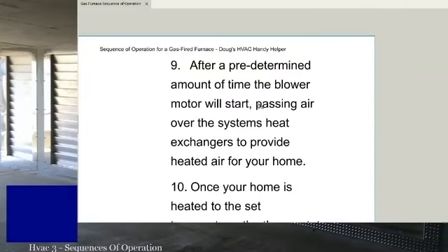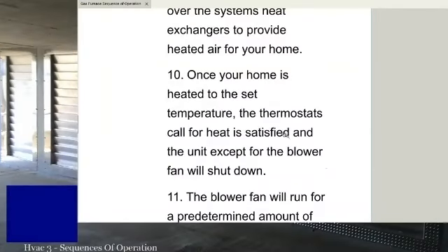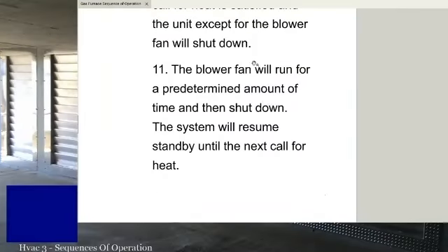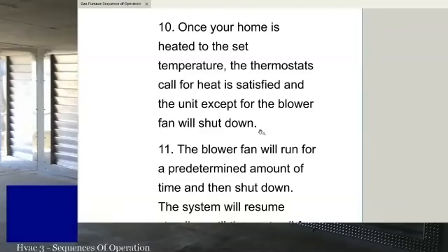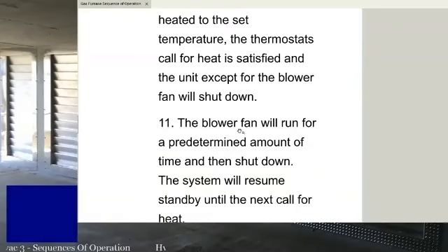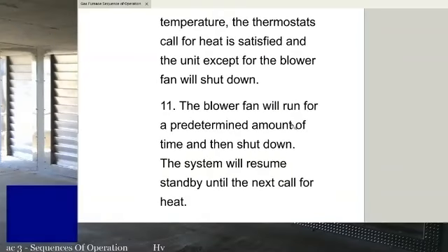All right. After a predetermined amount of time, the blower motor will start, passing air over the heat exchanger to provide heated air. Once the thermostat is satisfied, everything shuts down except for the blower. Sometimes the induced draft motor will run for a short period of time afterward to make sure all the gas is out of the combustion chamber. So that's a post-purge. A lot of especially bigger equipment has a pre-purge and a post-purge on the induced draft. Pre-purge makes sure all the gas is out before it fires. The post-purge makes sure all the gas is out before everything shuts off. Blower fan will run for a predetermined amount of time and shut down, and then the system will go back in standby.